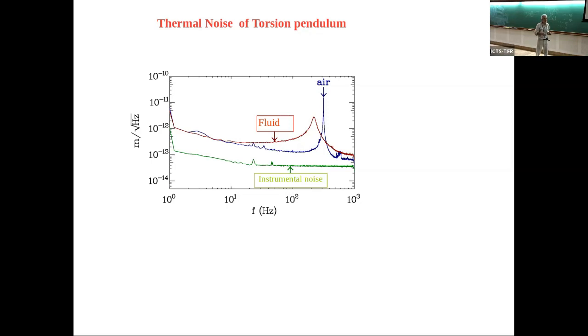And I can show many measurements. For example, as we are discussing all these kinds of things, suppose that now I'm taking an AFM cantilever that is oscillating like this, very small, and I do this just with monocrystals of silicon. Then you see that this effect completely disappears. But now I take the same one and I put just a layer of gold, and then you see that there's a 1/f noise that appears. That is just due to the fact that, as you know, gold is very plastic, and so you have a lot of dissipation inside. And so then you can describe this as an imaginary part of the Young modulus.